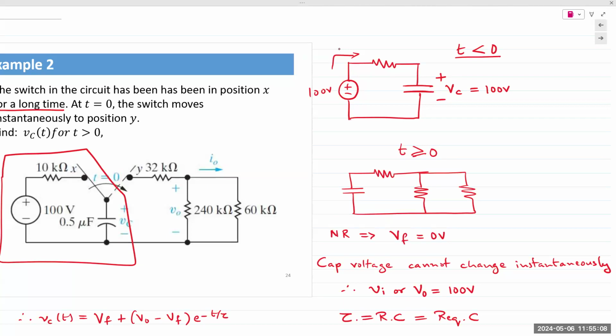Now, if there are multiple resistors connected in the network, then yes, some of the current would be flowing to the other resistors and there would be a voltage drop. Let's say there was a resistor in parallel. You have to look at the circuit without the capacitor connected. So we have to look at the Thevenin voltage from the terminals where the capacitor is connected. If you remove the capacitor, what is the voltage between those terminals? Analyzing the Thevenin voltage between those open terminals. We did this problem earlier.